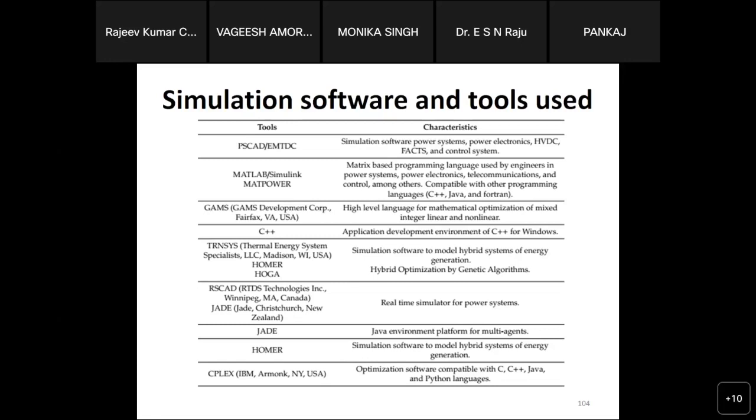We can go for co-simulation, using a combination of any two software tools. Suppose we are implementing some algorithm in one software while the virtual power network runs in a real-time simulator like RSCAD, PSCAD, or OPAL-RT. In that case, we can go for co-simulation such as software-in-the-loop, hardware-in-the-loop, or power hardware-in-the-loop simulation. Likewise, we can develop different control algorithms, energy management system algorithms, and other applications, and verify all these before going for field experiments or real-time application.